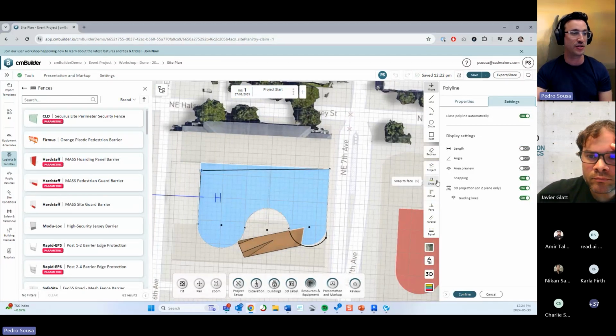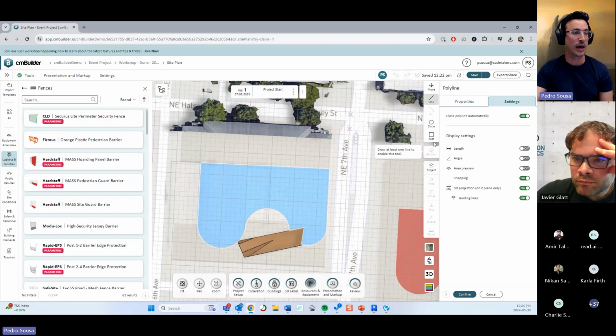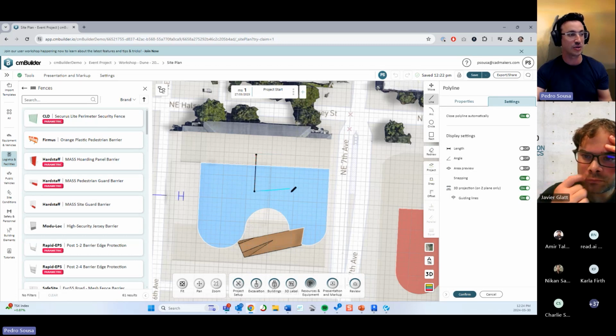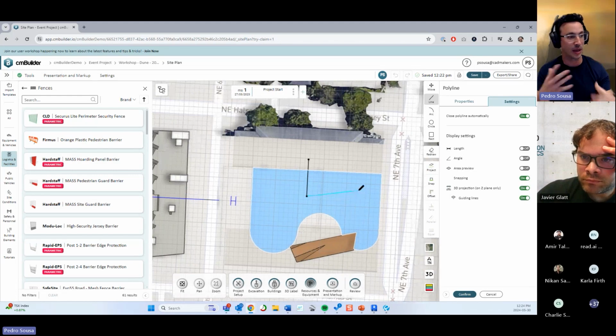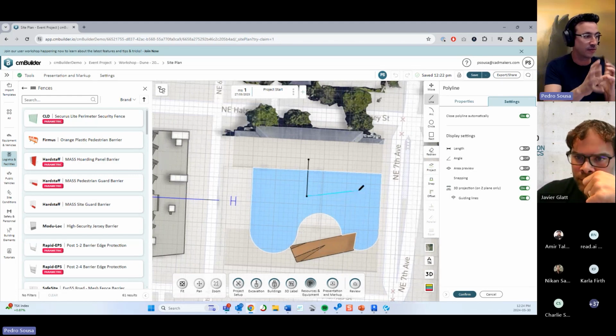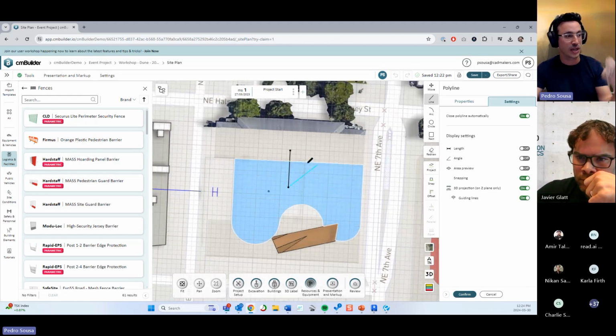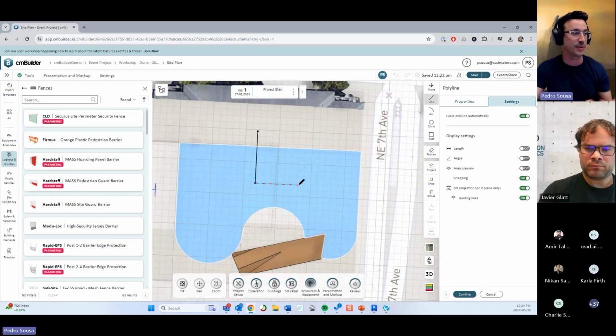you turn on the snapping feature, it will make your lines and elements snap to the vertical and horizontal references of your sketch. So this is something that sometimes people don't know exactly what's going on, why your line is being snapped to these references. You just need to go in your settings and turn on the snapping, then you can freely add points now.